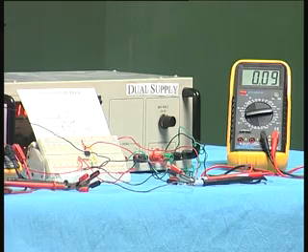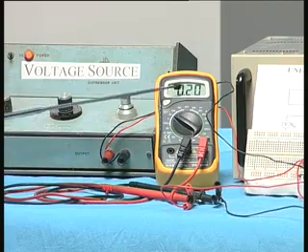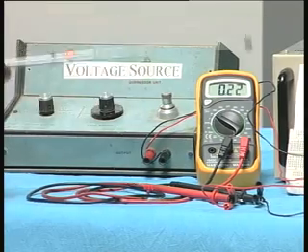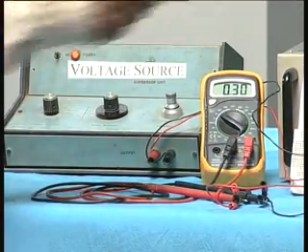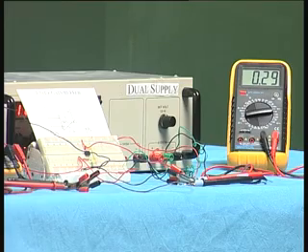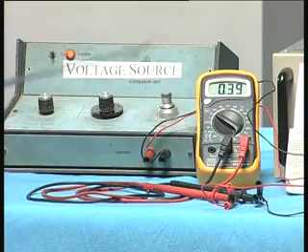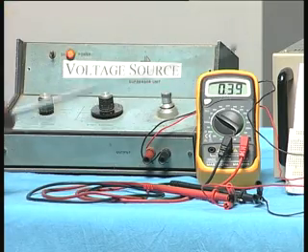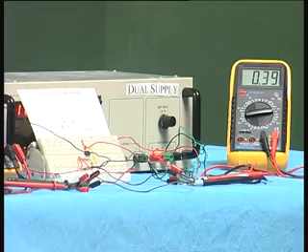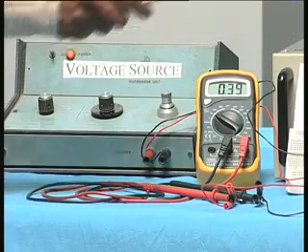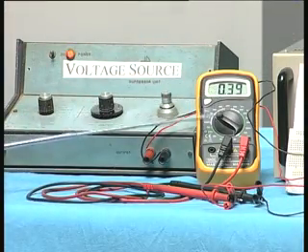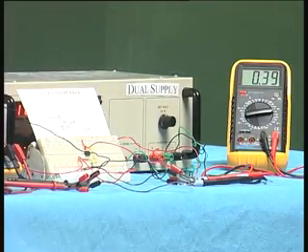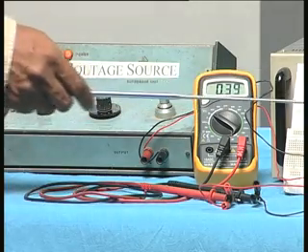Now if I put it into 2, that means I give 200 millivolts, the output is also about 190 something. 300 millivolts, the output is also about 0.29. So there is no difference between the input and the output, they are almost equal. The input is 0.39 here, the output also is 0.39 here. And you can also see the polarity is the same: the output is positive and the input voltage is also positive, because it is a non-inverting amplifier.